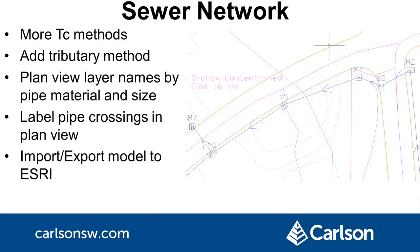Sewer Network added more time and concentration methods, including Maricopa County. Also, there's a new method for adding a tributary pipe and fitting it into an existing pipe run. For plan view labels, you can automatically use different layers by pipe material, size, and system. For pipe crossings, there's a new option to label the elevations and separation in plan view. And there are new routines to import and export the sewer model to Esri.